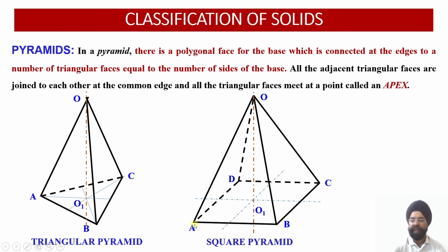In the case of a square, 4 corners are there, so 4 plus 2, 6 points you have to deal with. In projections of an oblique pyramid, for every construction, front view and top view, 6 points each, so only 36 points will be required to complete a question regarding a square pyramid. So questions regarding square pyramids consume much less time compared to problems related to prisms. So let us once again work out the terminology.